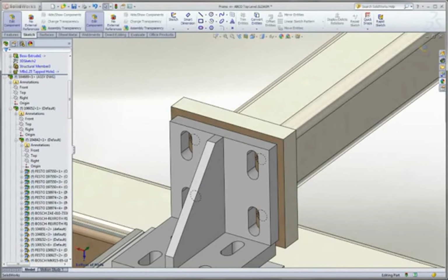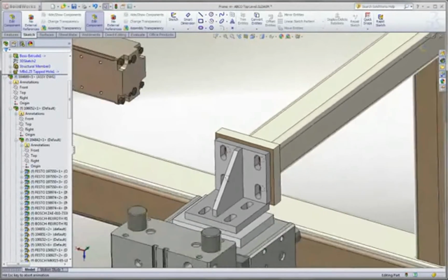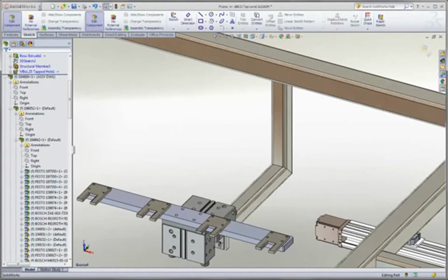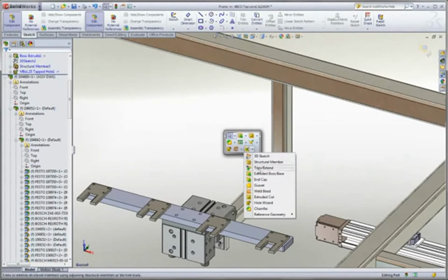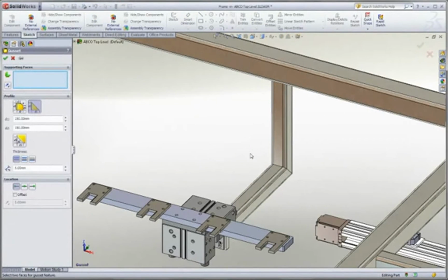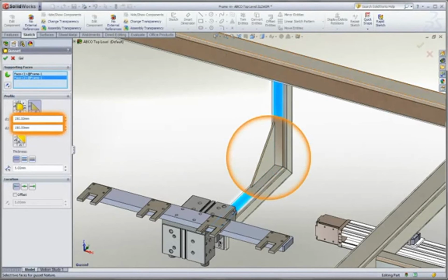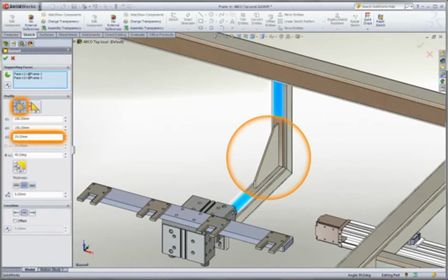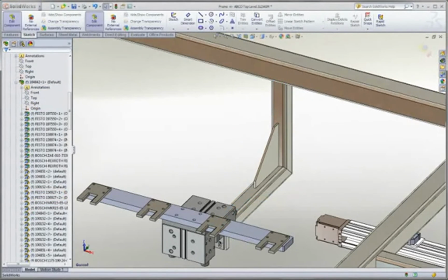Automatic alignment made simple. Gussets are an easy way to strengthen structural designs, and these should be just as easy to create and modify in your design tool. Like all of the other tools we've seen so far in SOLIDWORKS, all the options are there to get you just what you need. These basics include overall size, location, chamfered corners, and thickness, just to name a few of the many options available for creating gussets.